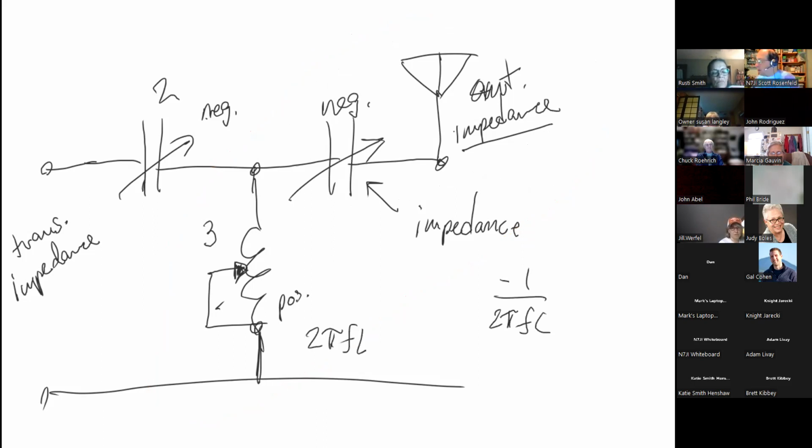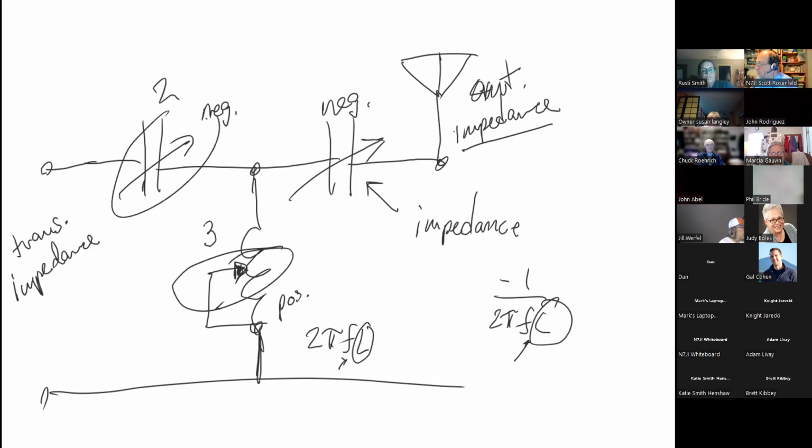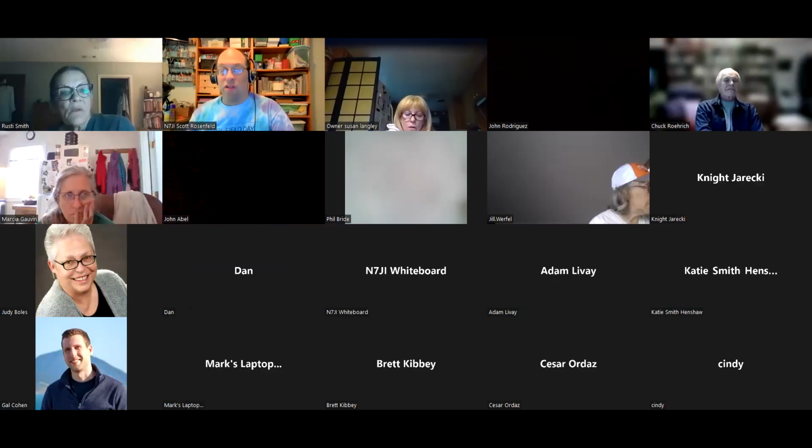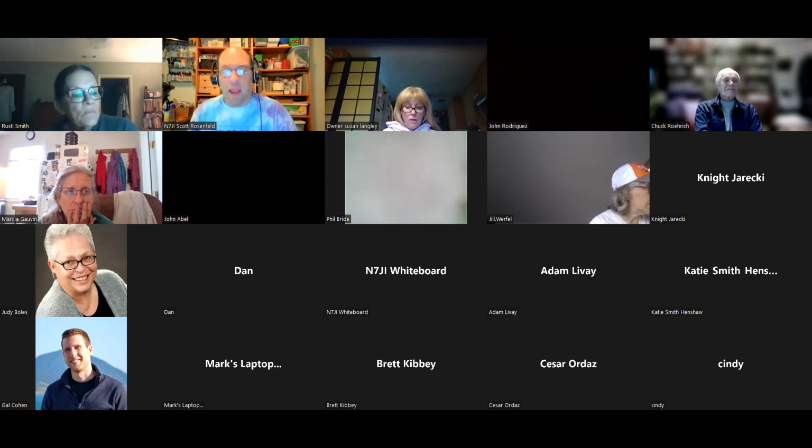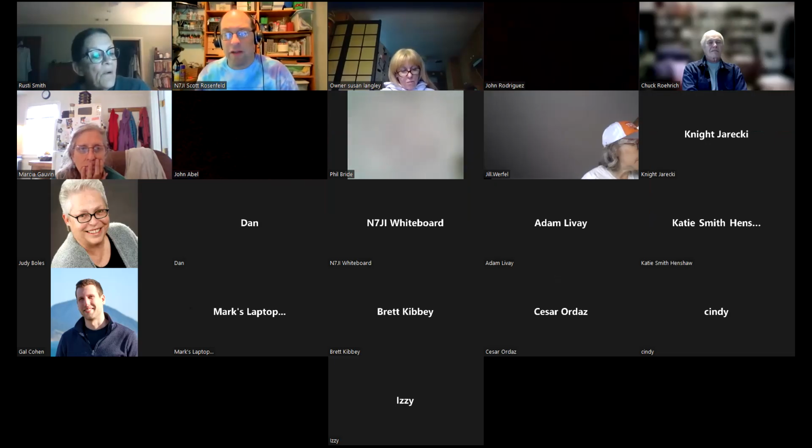So notice we have our frequency that shows up in both, and we also have an inductance which is now variable, and a capacitance which can be varied twice, 2 different ones. So what we can then do is use this to create something called a T-type antenna tuner. And that looks like this.